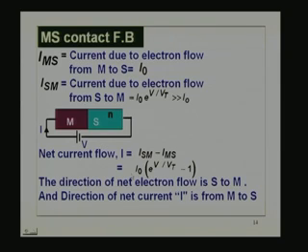That term goes off, and you will get I naught. You put a minus because of the direction of current you are assuming. When you write this equation, you write V as metal positive and the current direction as current entering into the metal as positive. So, when you reverse bias, that becomes minus I naught, telling you that the current direction is reversed.